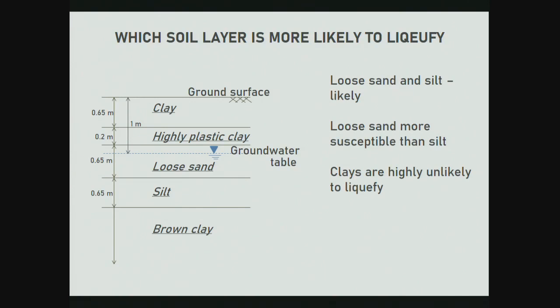But still, you need a trigger to cause liquefaction. What I mean by that is, if you artificially make this soil profile in a fish tank and you leave it there, nothing will happen. You need a trigger. You need earthquake vibrations. You need some source which causes disturbance. But you need to pass a certain threshold, because each soil will have a certain resistance against liquefaction. This threshold needs to be breached, and only then will liquefaction occur.